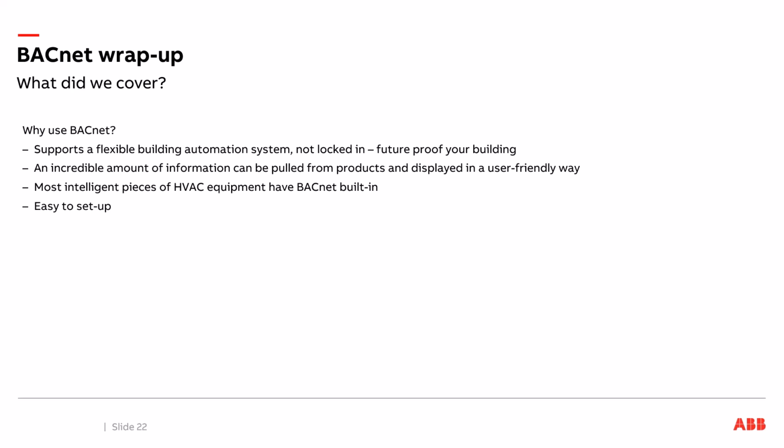And then lastly, it's not tough to set this up. Granted, the controls contractors and the VFD startup techs, for VFDs as the example earlier, will be the ones doing the programming. It is not complex. It is not hard to set up this equipment for BACnet. So there really shouldn't be any excuses not to use BACnet. The cost is not high. The setup is not high. It's just a very friendly protocol that can pull a lot of information from products, bring it to you on your operator workstation, and allow you to see exactly how the building is operating for your HVAC equipment.